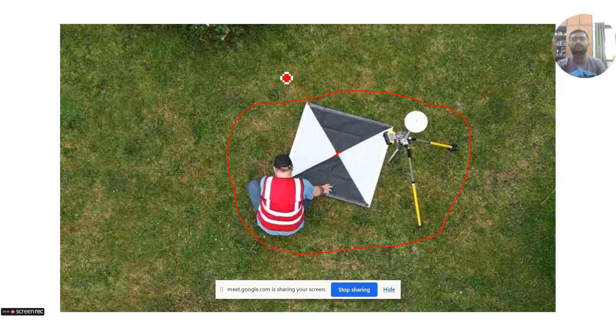If you do not have any permanent structures such as buildings in your terrain, then you put these kinds of sheets using which you find the GCP. But if you have the structures, there is no need to put these. Did you get my point?